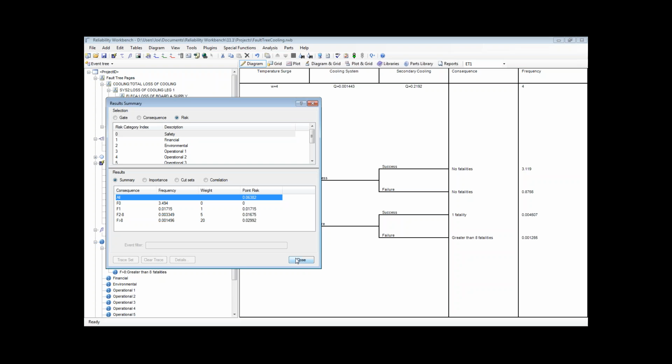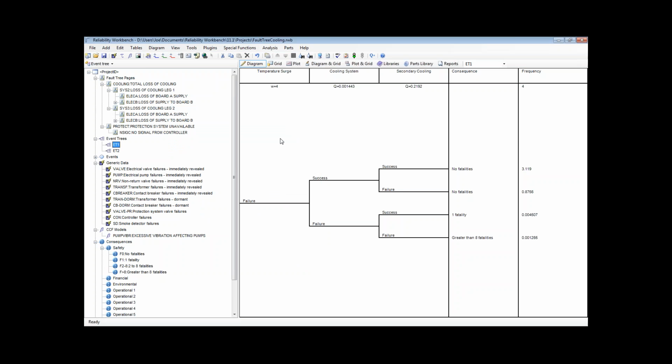Okay, any questions on the results before we move on? I'm going to take a quick look here. And back to the event tree, and when you're adding multiple branches, is it true that the total would equal 1? The interesting thing is the program doesn't necessarily enforce that. Typically, you'd set it up that way when you're creating the basic events, or that would apply to the partial event failure branches. Typically, you construct them in such a way that their probability is 1.